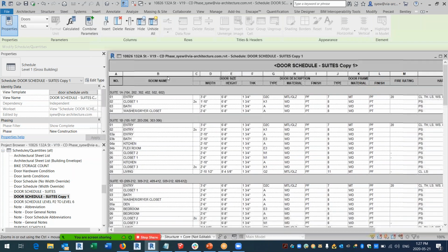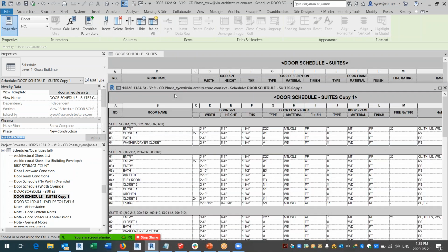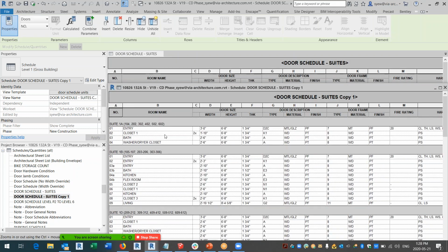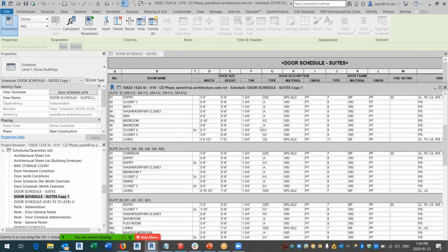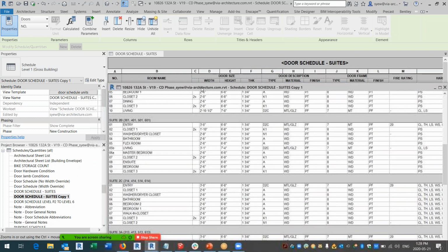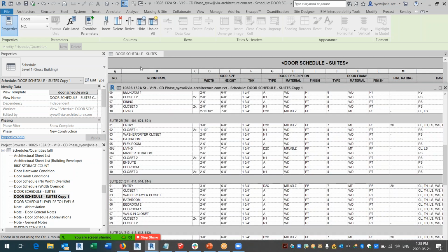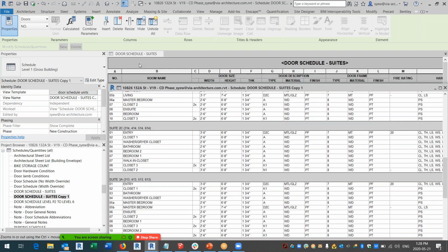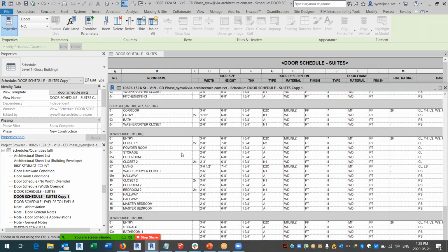Next, you're going to put it somewhere closer to this particular place, so you notice that you're aligning. And when you scroll down, you notice that this top part of the schedule remains. Then you can go down there and modify your schedule. This is the quick trick that I usually like to use: you just duplicate your schedule and align it to the underside of this header. The original is in the background, and you're basically just moving this.